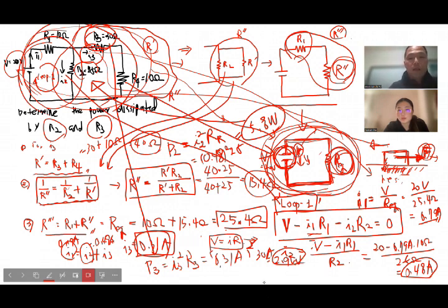For finding the individual voltages of each resistor, instead of using the junction rule, I used a different way. I know the fundamental Ohm's law, V equals I times R. So essentially what I did, I said 20 is equal to I multiplied by the total resistance, and then I was able to find the current.